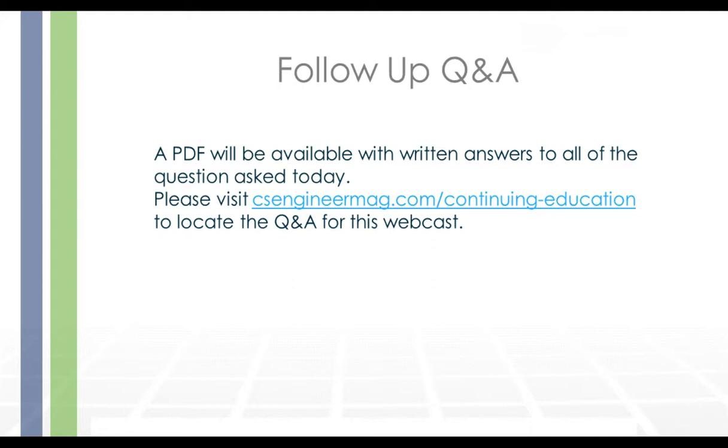Next question. In OpenBridge Modeler, can you create custom abutments with wing walls? It's not available at the time, but this is Raul. You can create really intricate abutments, including the wing walls. The nicest thing is that you can place them in a DGN level. In OpenBridge Modeler, we're able to look at them and place them in the correct station and offset and elevation, okay?